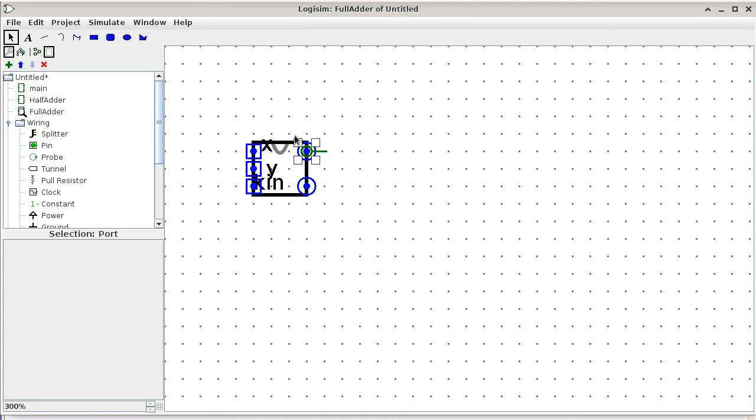Okay, so I have moved the pins in the appearance, but I haven't really moved the pin in the actual circuit definition. Yes. You mean this line here? That is the home position of the entire quote-unquote chip. So the chip has its own little home position. When we refer to the location of the circuit appearance, that is dictating that. It's also dictating the facing. So right now, the circuit is facing east. This is what it looks like facing east. When you change the facing, you're changing the orientation of that line.